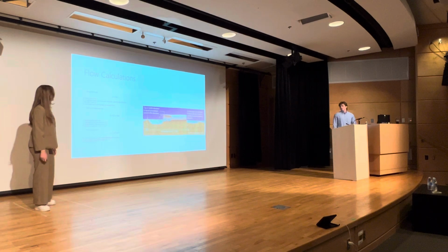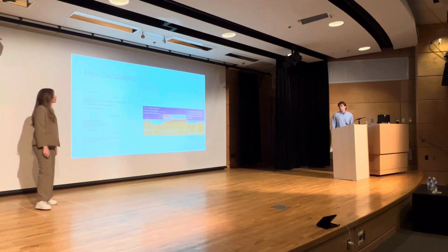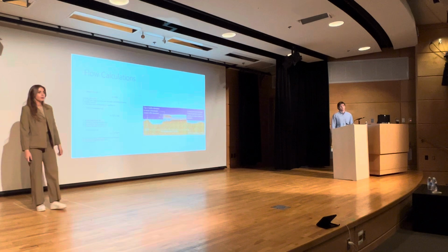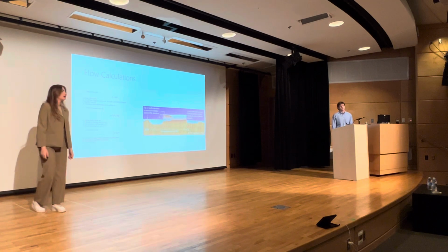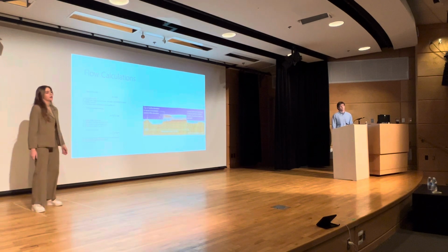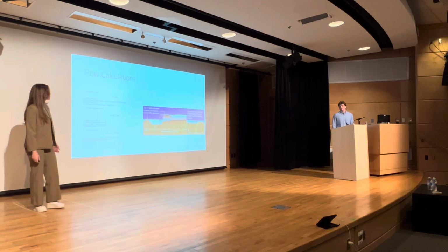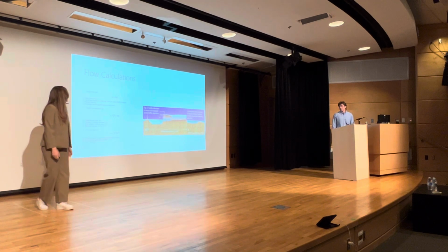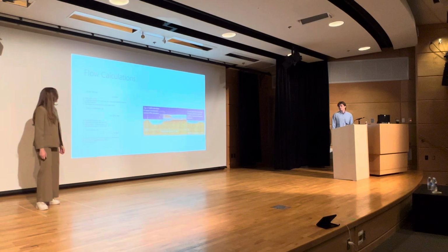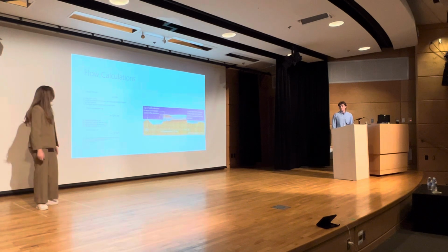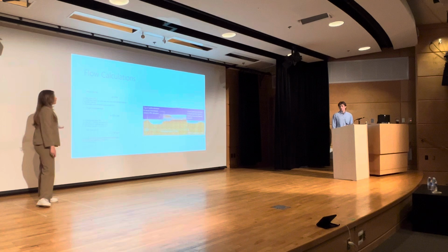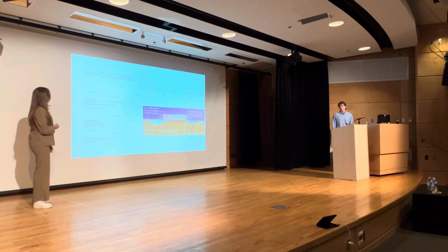These are some flow calculations. Flow calculations are important to not over-design or under-design the culvert. If we over-design the culvert, it can lead to unnecessary costs. And if we under-design it, it can lead to infrastructure failure or the fish not being able to go through it. These calculations we still have to research, because I'm sure that the baffles do change a few of them. But this is our design flow calculation.